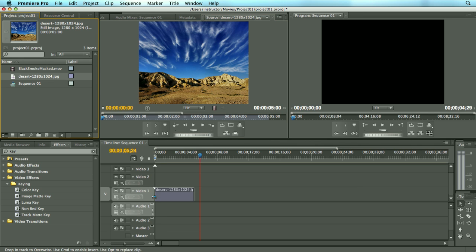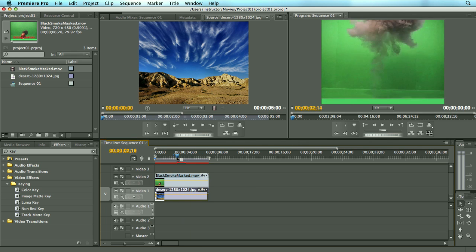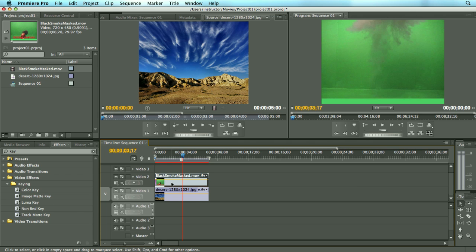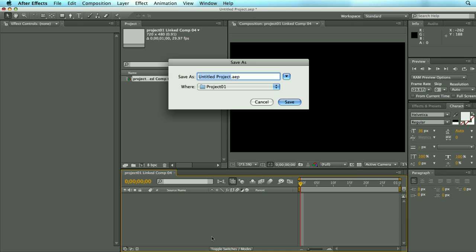I'm going to bring both of these to my timeline, resize my background, and I have a green screen background here that needs to be removed. I could use some of these keyers inside of Premiere, but I don't find them to be very effective. So instead, I'm going to edit this clip in AfterEffects. With Dynamic Link, all I have to do is right-click and come to Replace with AfterEffects Composition.